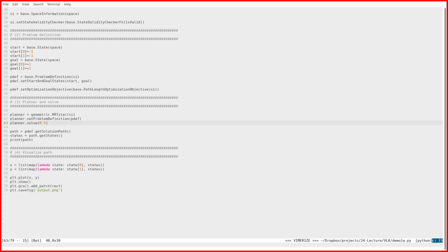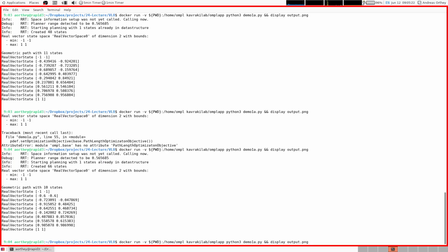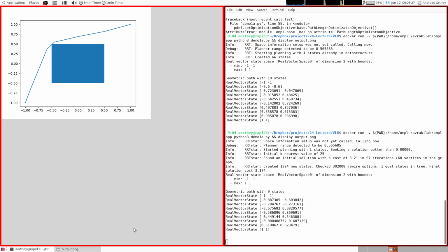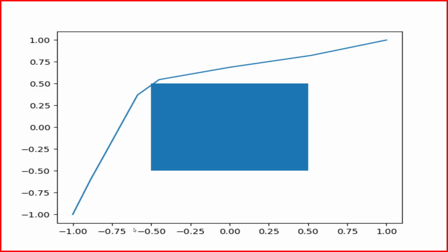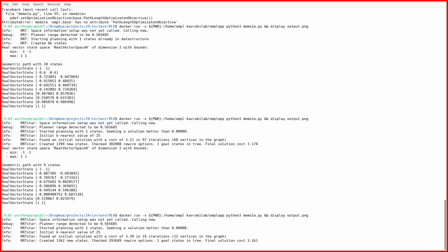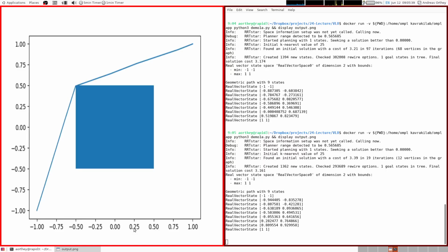And this optimal planner will just plan for the whole time here. So let's set it to 1.0 seconds, and it will not just return you one path, but it will also try to optimize the path over time. And so it will take a little bit longer, but in the end, you get back a path which is optimal. And if you run it again, then again, RRT star will optimize your path, and it will return you this optimal solution here to go from the lower left corner to the upper right corner.